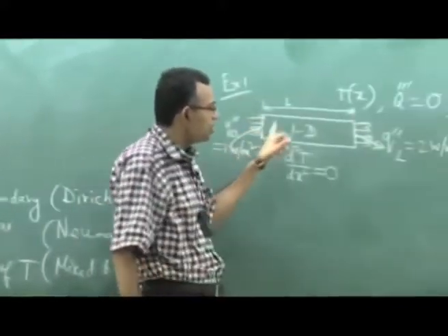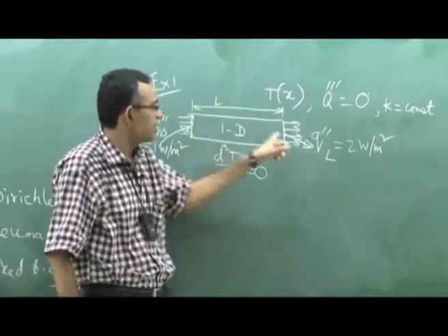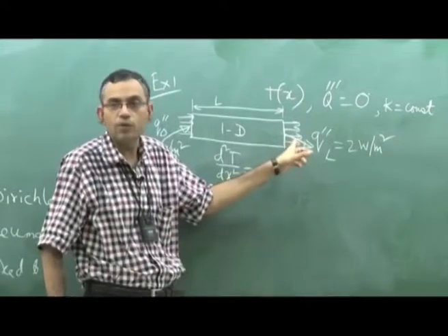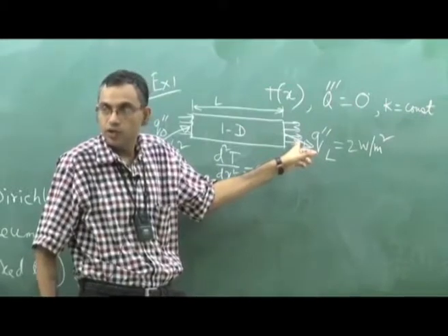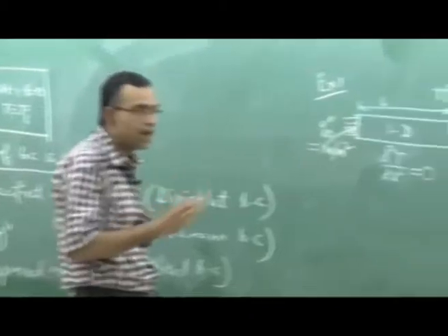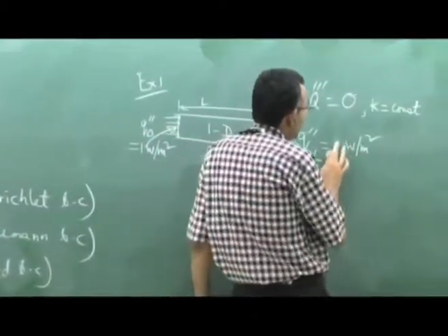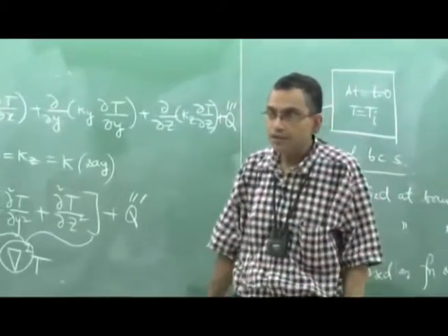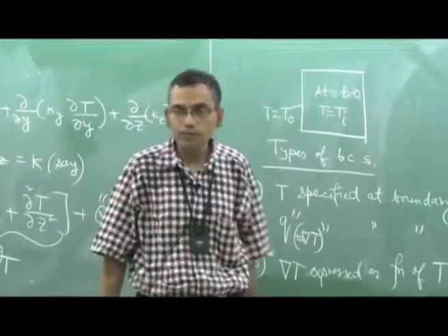So, when there is no change with respect to time and there is no heat generation, whatever comes in, the same must go out. So, this is a physically inconsistent problem or an ill-posed problem, right. So, any boundary condition you give is not a valid boundary condition. Now, you may say that, well, I have understood it now, let me give this as 1 watt per meter square, right. Then it is physically consistent. Now, can you solve this problem?